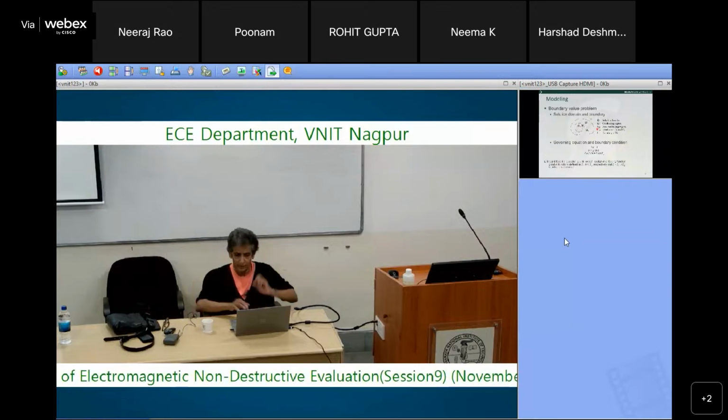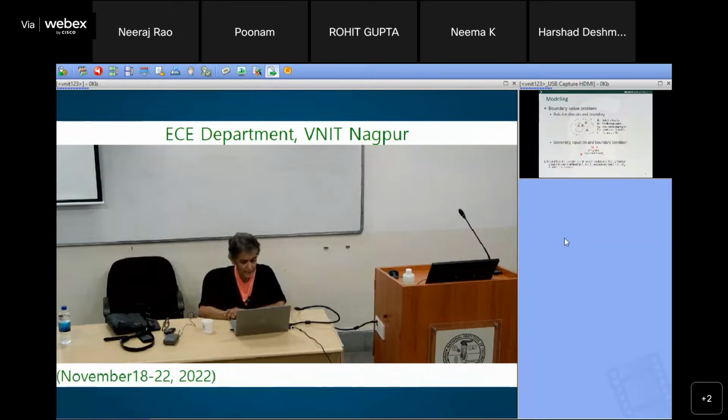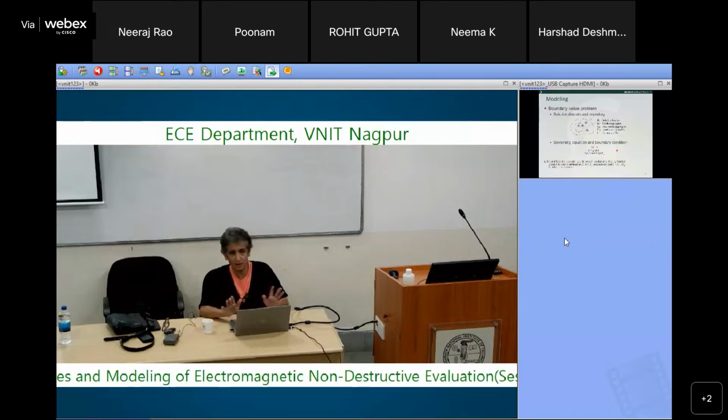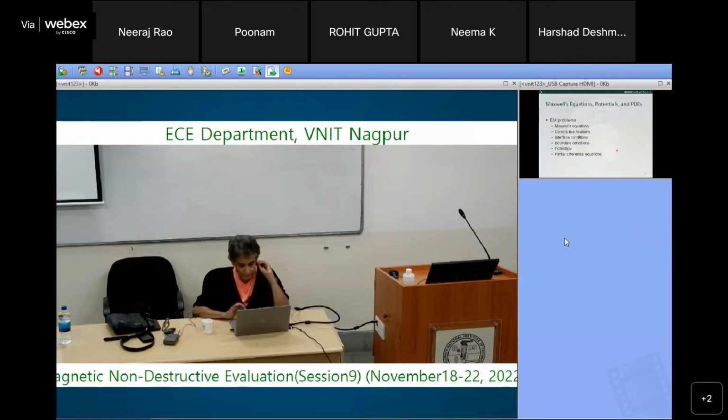And the governing equation can be written in operator form, where you have LU equals F, F is the source, U is the unknown, and then there are boundary conditions where U is defined on some outside boundary, that's the Dirichlet boundary condition. You can also apply the Neumann boundary condition on some interface. So this is how a generic description of modeling goes.